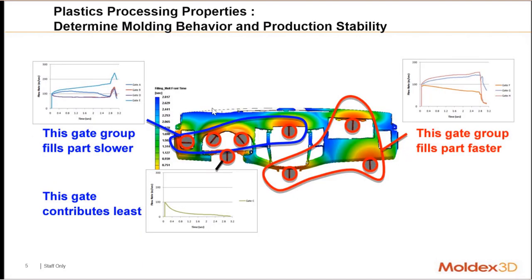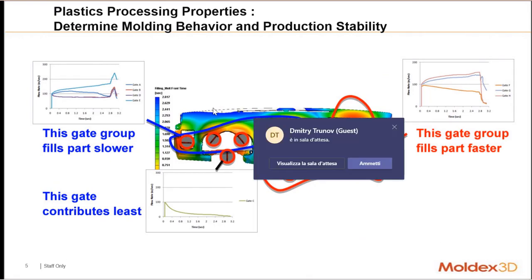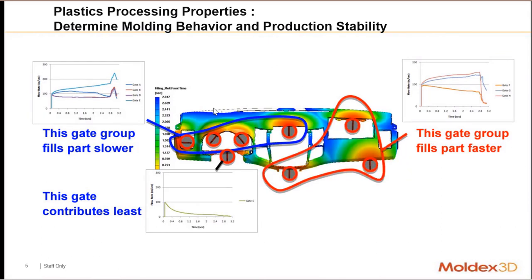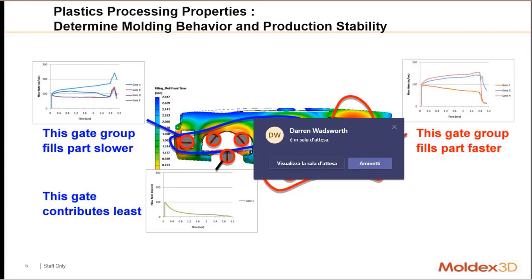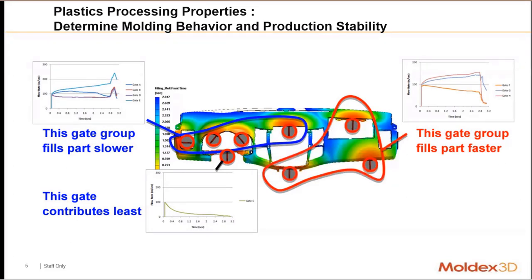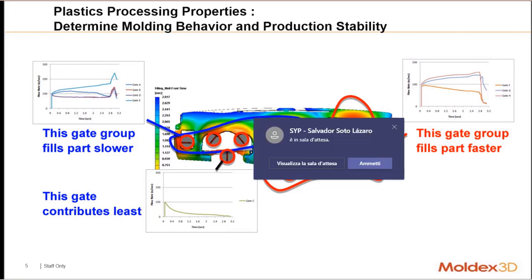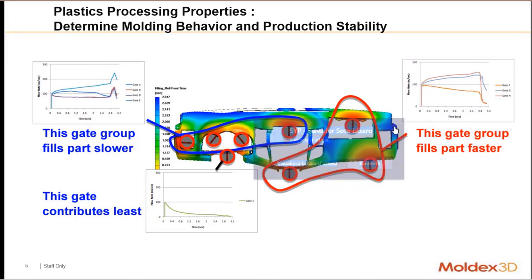We should focus more on the mechanical property first. And the second is the processing properties. I think this is a typical property everybody in our business knows, and how to persuade users why viscosity and thermal properties are so critical for molding, because they determine the molding behavior and the production stability. Many molding defects, such as short shot, flash, hesitation flow or flow marks, are highly related to the processing properties.